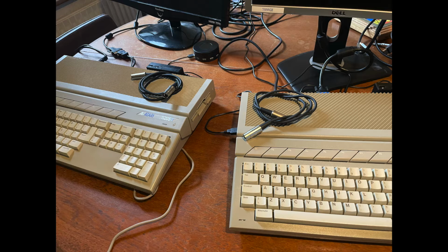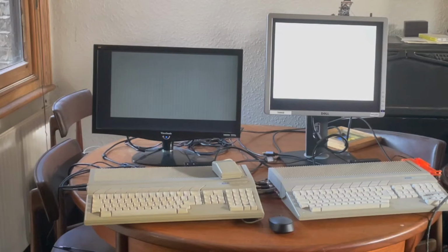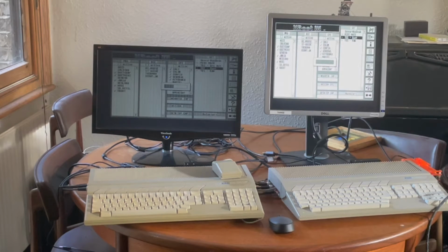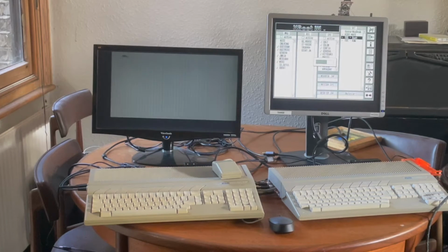The other aspect of this is data transfer speed. The ST line of computers had a maximum serial port baud rate of 19,200 bits per second. Now, while hardware hacks were available to take this up to 38,400, that required you to be soldering iron and bodge wire savvy, and it was not for the faint-hearted. MIDI, on the other hand, is an industry standard. It runs at 31,250 bits per second, stock, so no soldering required. Plus, of course, you can play multi-user MIDI maze. Hey, that's what it was all about back then.